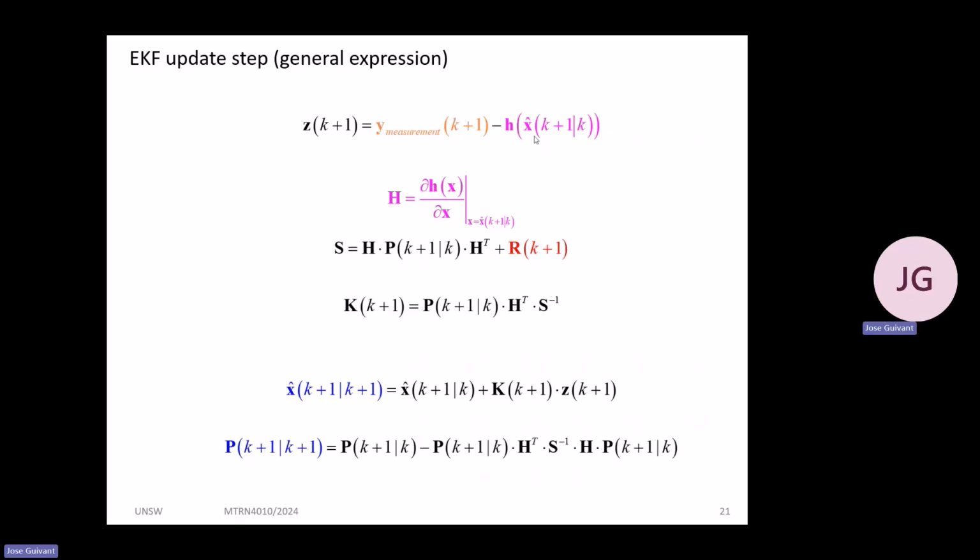So we apply the output equation, and that produces the expected output variable. Okay, and we compare this with the measurement of the output variable. And you could be sure both are lying a bit, because this measurement is coming with certain pollution due to the noise coming from the sensor.